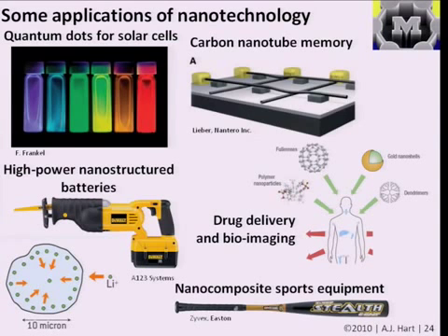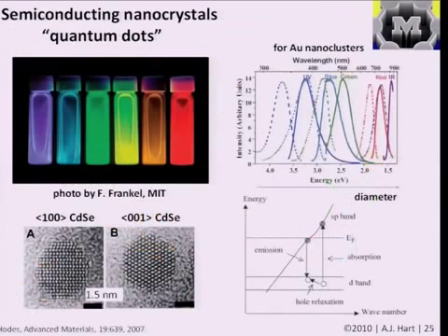Also, the incorporation of small amounts of carbon nanotubes in composites for golf shafts has made them lighter and stiffer, yet providing a better feel, making a slightly better golf shaft. In combination with it being, quote, cool nanotechnology, it has been an extremely successful product for the shaft company Aldila and the company Zyvex, which developed the chemistry to disperse the nanotubes and mix them with polymers to get that improvement in properties. That said, the improvements seen in these composites with the current way that nanotubes are made and mixed with the polymer are, say, 2 orders of magnitude below what we might have if you could grow continuous long nanotubes with the true strength and stiffness of the individual structures. That remains one of the big challenges of controlling the manufacturing processes a lot better.